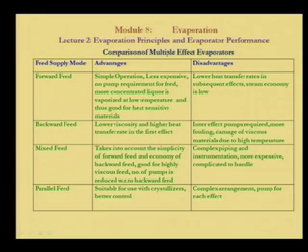So, fouling possibility is more in backward, and damage of viscous materials due to high temperature, that is what was told. And for mixed flow cases, mixed feed supply takes into account the simplicity of forward and economy of backward feed, and is good for highly viscous, and the number of pumps is reduced with respect to backward feed. Okay. And complex piping and instrumentation, more expensive, complicated to handle.